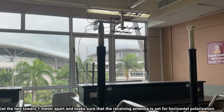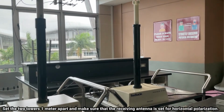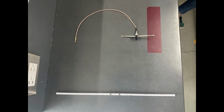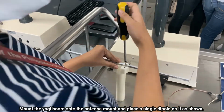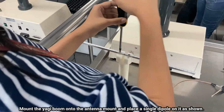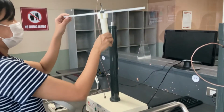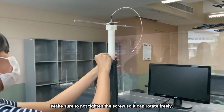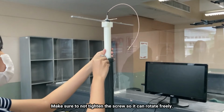Set the two towers 1 meter apart and make sure that the receiving antenna is set for horizontal polarization. Mount the Yagi boom onto the antenna mount and place a single dipole on it as shown. Make sure to not tighten the screw so it can rotate freely.